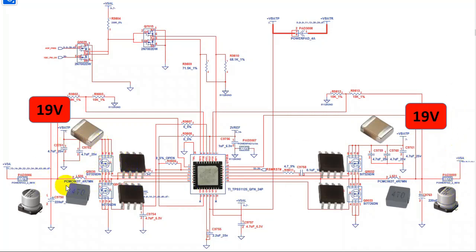So the same working principle for 3 volts always. So we have the IC, we have two MOSFETs, or voltage regulators. Here we have 19 volt that will pass through these ceramic capacitors, then goes to this MOSFET or voltage regulator. Then here we will get 3 volt or 3.3 volt. So the 3 volt will pass through this inductor in order to increase the current.